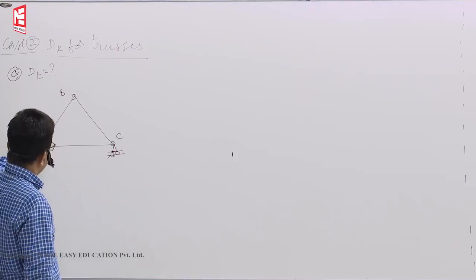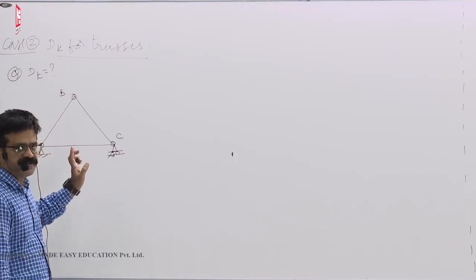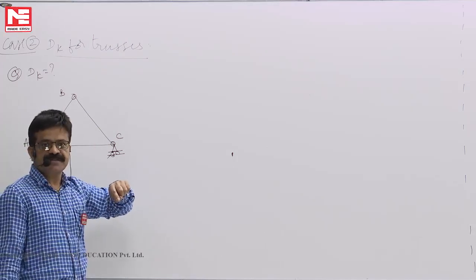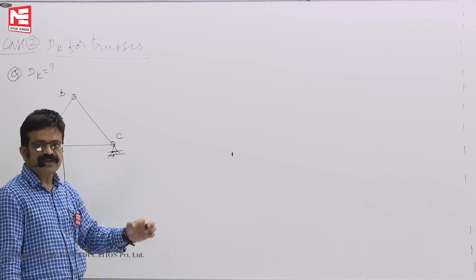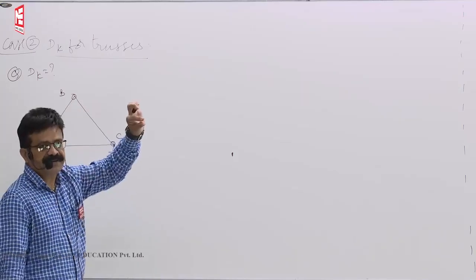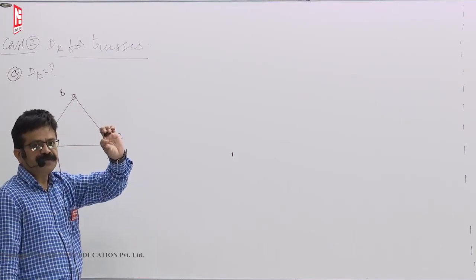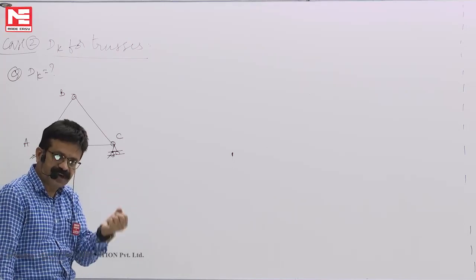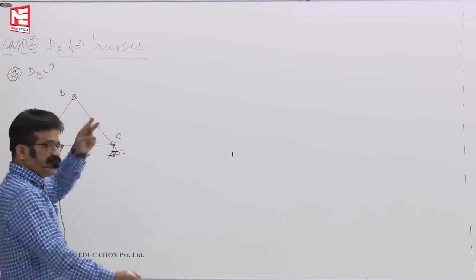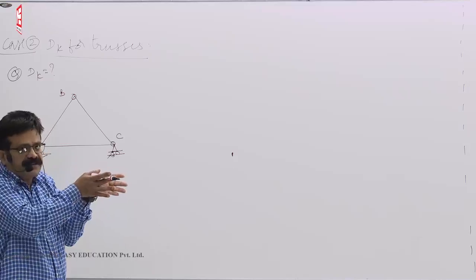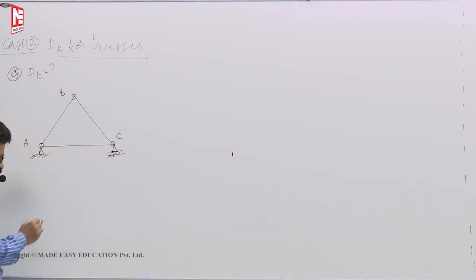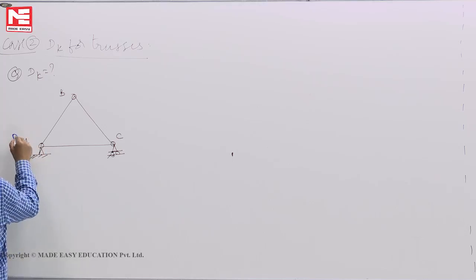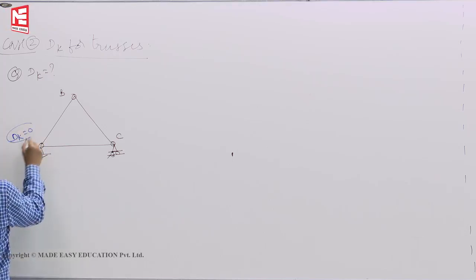So theta 1, theta 2 not possible. Even xy displacements, translations are also not possible at A because of the pin. Pin cannot move because it is connected to a hinge support, means it is connected to the ground with the help of two triangular plates. Front and back triangular plates will be there. That means here dk is 0 at A.